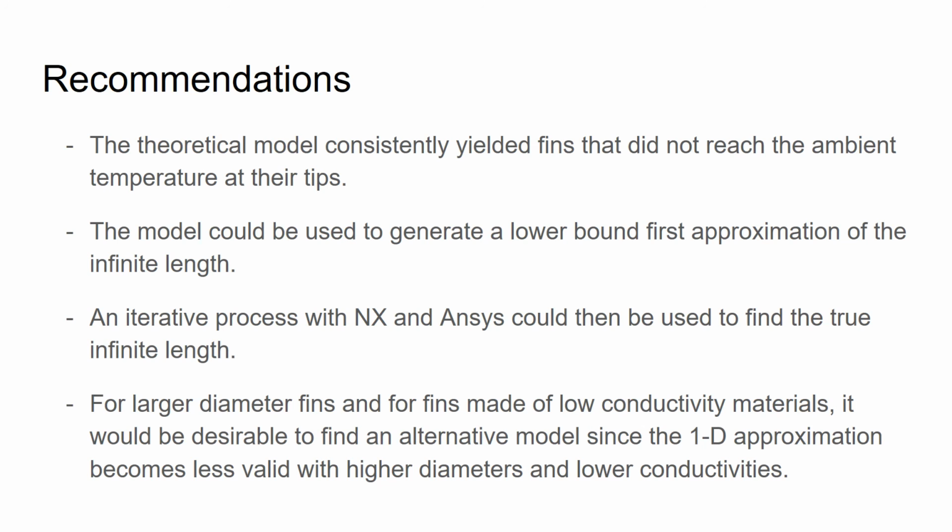It should also be noted that for larger diameter fins and for fins made of low conductivity materials, it would be desirable to find an alternative model because the 1D approximation becomes less valid with higher diameters and lower conductivities.